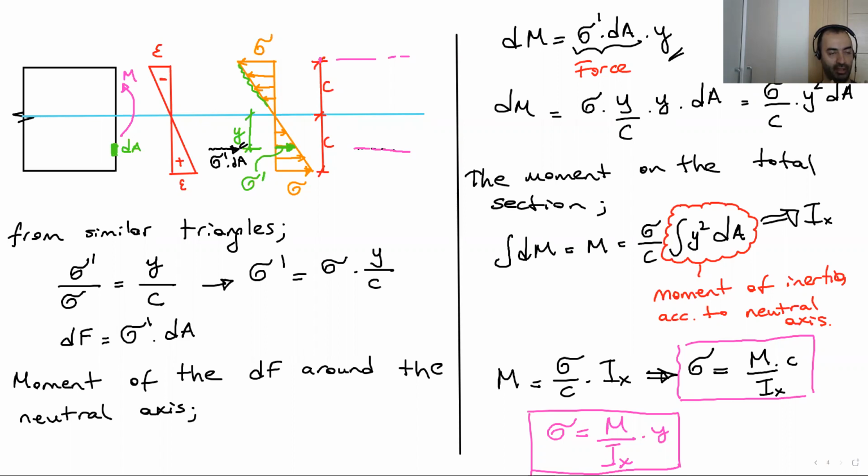But you need to keep your eye on the stress distribution, on the bending moment, where we get the maximum stress, at the top edge and the bottom edge. The edges are important for us. We are going to get the maximum and the minimum stresses over there, because when we go inside, we are getting closer to the neutral axis.